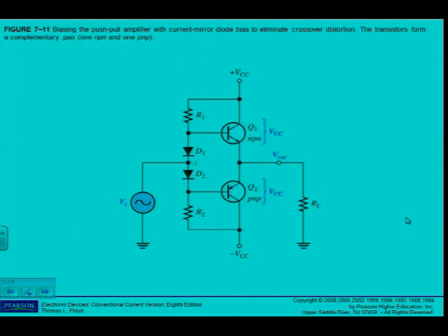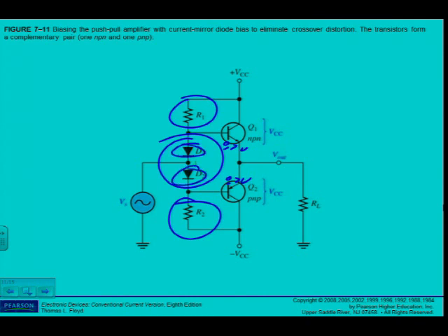See what I've done. I've done some biasing. I've got the voltage divider here again, but I'm also using two diodes. What was the problem? The 0.7 volts here. What is the volt drop over a diode that is forward biased? 0.7 volts. But what do we know? It's not exactly 0.7 volts, and that's where the difficulty comes in. I have to find a transistor and a diode which has approximately the same voltage drop over the forward biased p-n junction.